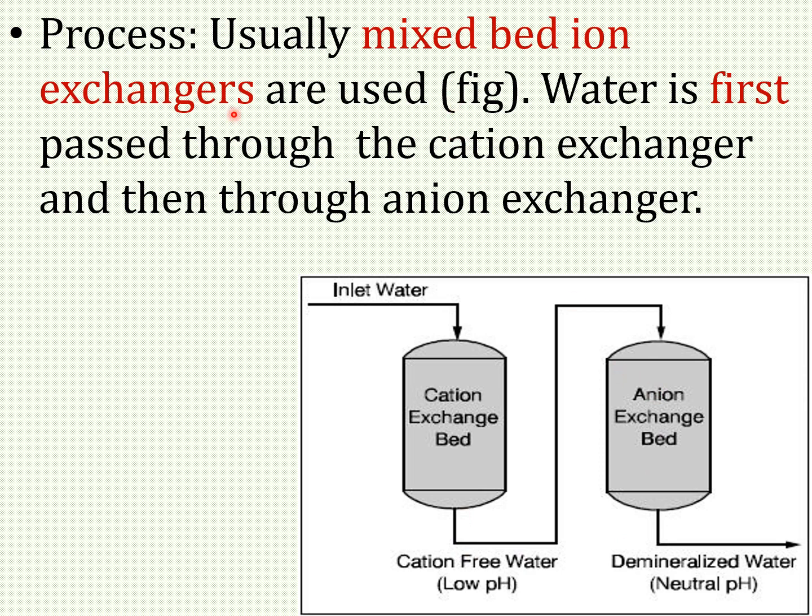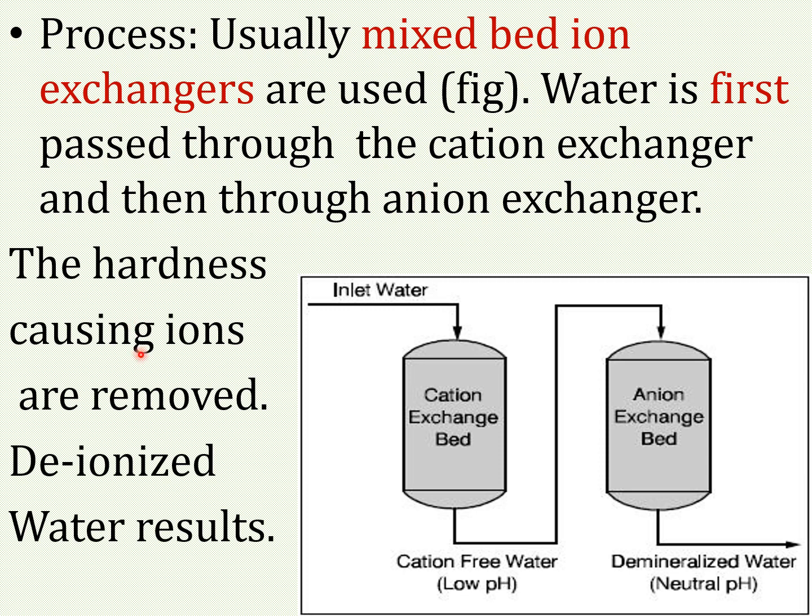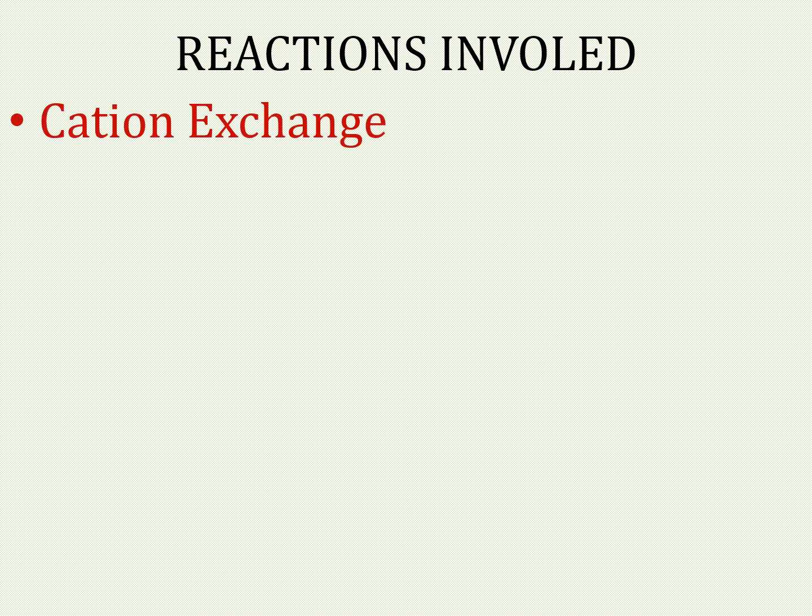Water is first passed through the cation exchanger and then through the anion exchanger. The cations as well as the anions are removed, and we get the deionized water, which will be collected from the bottom of the bed. Here I have just consolidated the equations.